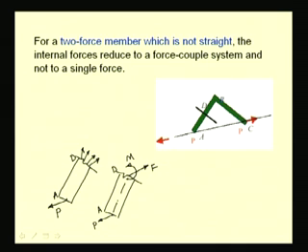If we consider this free body diagram, for the portion to be in equilibrium, the sum of these two forces has to be 0 and the moment of this force P about this point should be equal to this anti-clockwise moment M that we have marked at D.